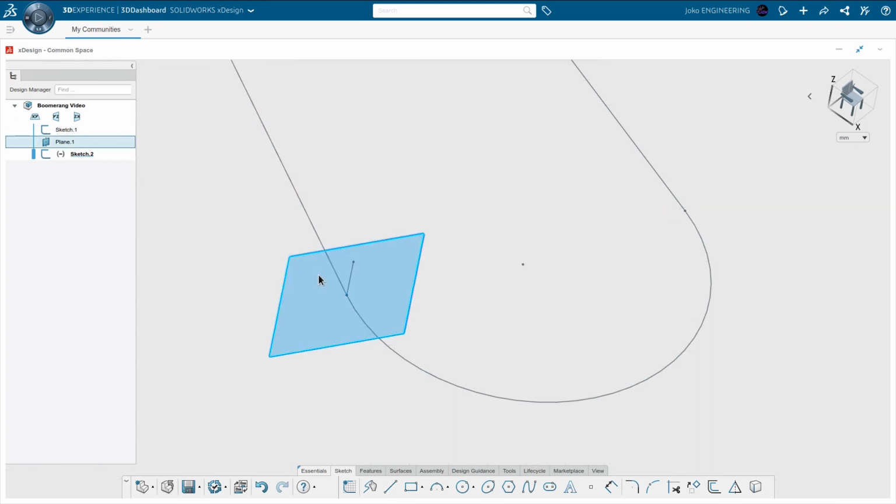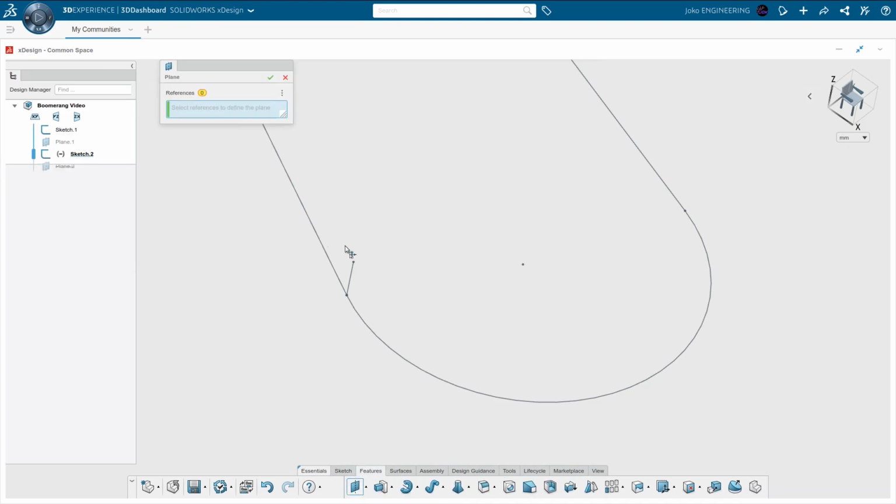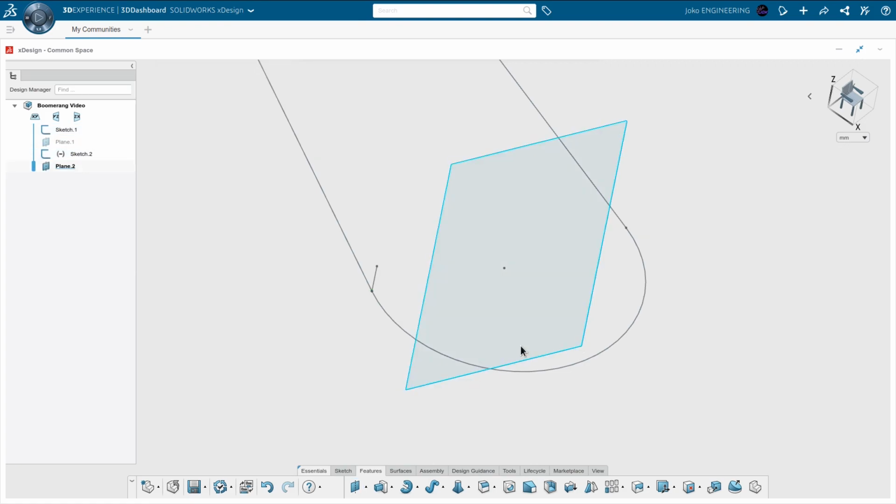All right, so I have this sort of redundant, strange sketch, but it gives me the point that I need. And then I'm going to hide my plane. Of course, just by clicking on something, you have the option to hide something. And we're going to add in another plane, because now we have 3 points to define a plane. And there we go, right? So there's some ways to define a plane like that.